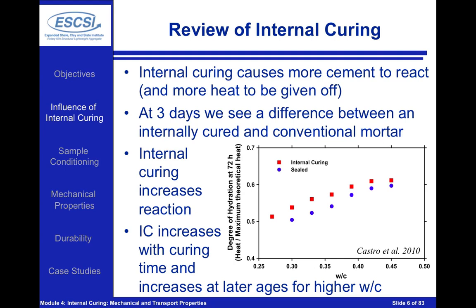And what we'll notice is there's a difference in the heat given off between the internally cured and the sealed concretes. Heat is a direct measure of how much reaction has occurred, so we can see that even at early ages, even as early as 3 days, we're seeing a fairly substantial difference in the amount of heat given off, the amount of hydration reaction, and this tells us that the internal curing is doing what its intention is. It's hydrating more of the cement.